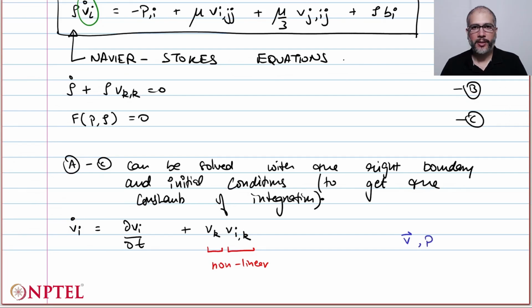I'll also get the pressure at the different points on the surface of the car, and using this pressure, I can calculate the form drag or the pressure drag, and using this velocity field around the car, I can calculate the viscous drag or the shear drag, and that will give me together a global quantity called the overall drag force on the car. And then I can improve the design of the car and then measure the drag again, and I keep on evolving the design so that I minimize my drag function. So this is typically how we use these quantities for something useful in design.